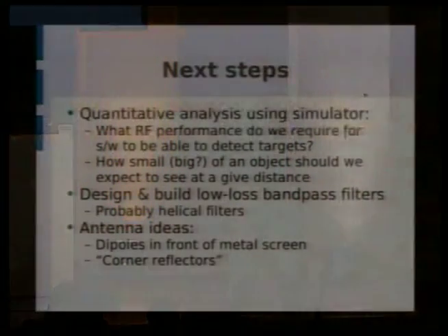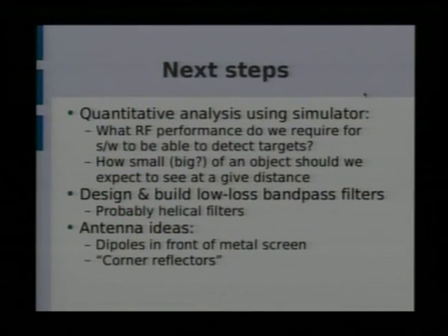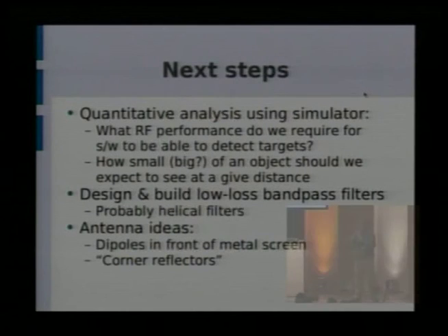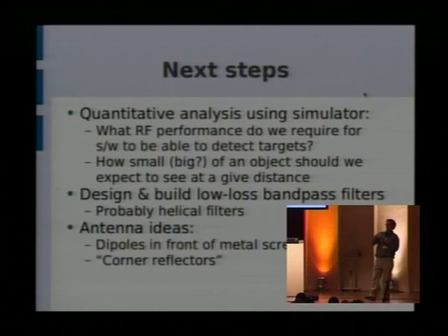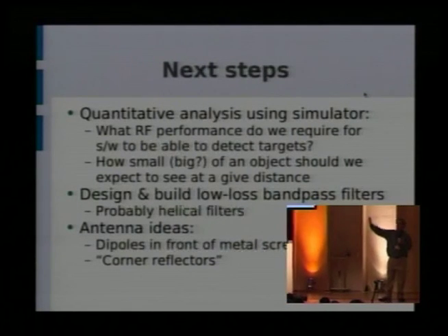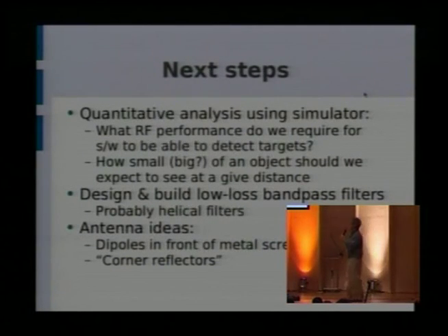So we looked at, and again, this is from looking at some of the literature, what did other people make work? Part of the problem may be that we're getting swamped out by the main path transmitter. This reflection off the airplane could be minimum 100 times smaller, 20 dB down from the main path. You've got a spherical wave that's propagating out, and it hits something, and then it propagates back to you. So it's small. So one of the tricks people have used is they need some way to keep the main transmitter from just hammering them.